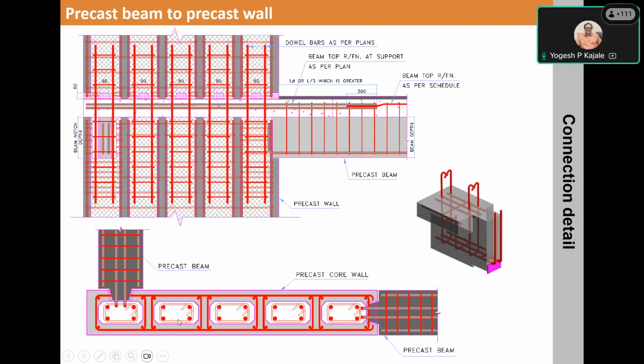The hollow core walls have reinforcement in the precast part. Then the outer leaf as well as inner leaf gets connected through the interconnecting concrete leaf. And in the hollow core, again the reinforcement is placed at the joint level. And then these hollow cores get concreted with the in situ concrete.